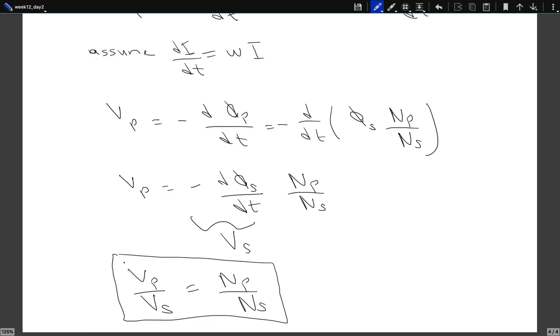220. 200. Step up or step down? Probably step down. You see, in Turkey, we have 240. Okay, so you want a step down transformer. You want to step down 240 volts to 110 volts. So that's why you want a step down transformer.